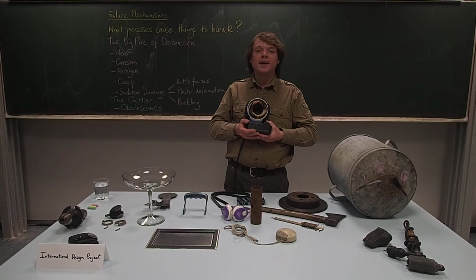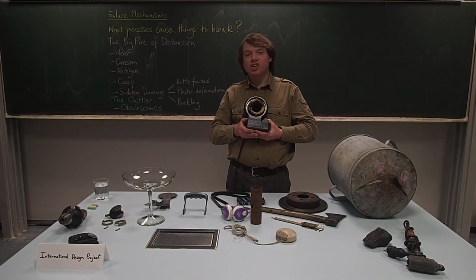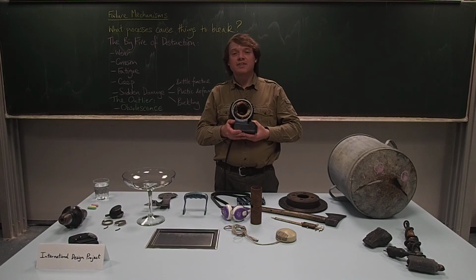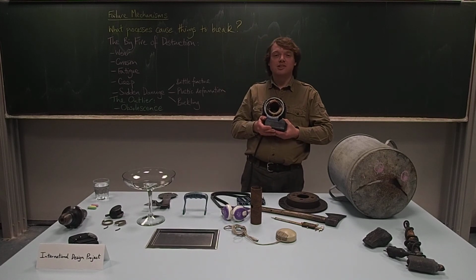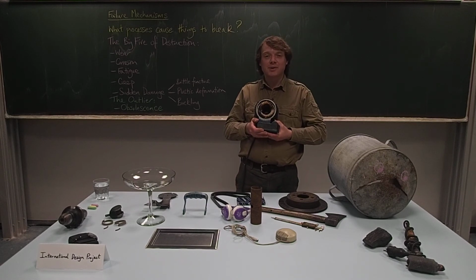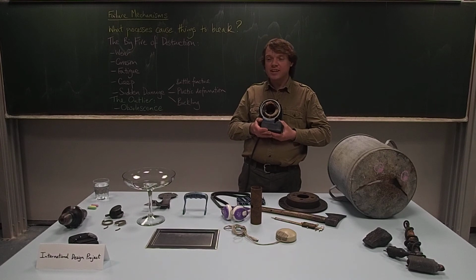It's more than the wire can cope with, more than the lacquer can cope with without charring, and it then started to conduct some electricity. The electricity has then found a new path, a short circuit, and it doesn't flow through the coils in the correct way. The motor then no longer develops a torque and overheats.